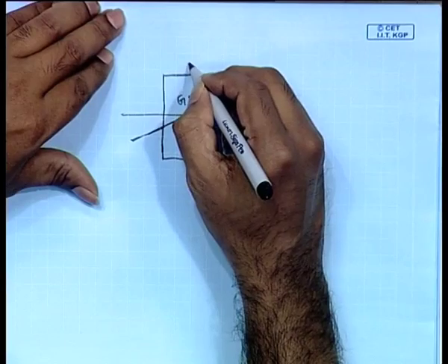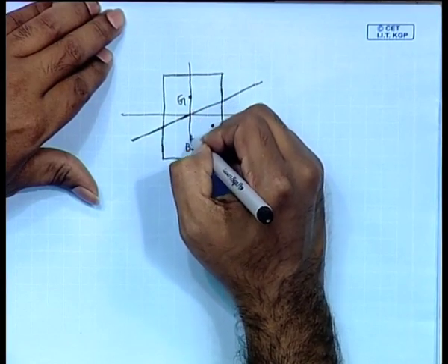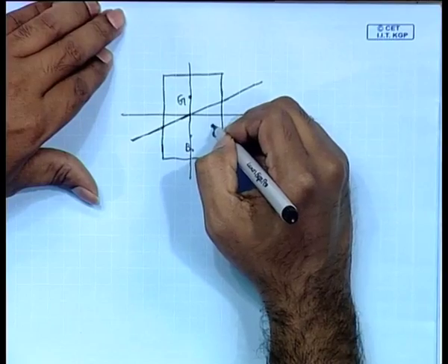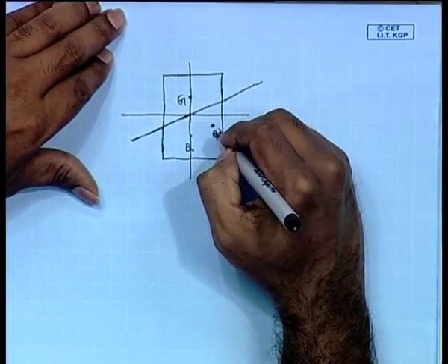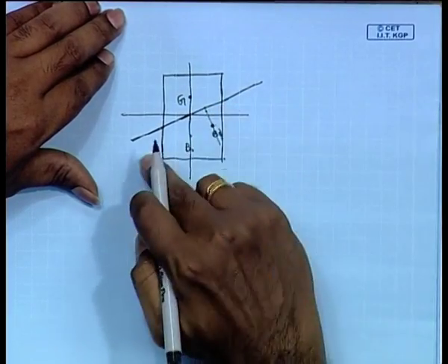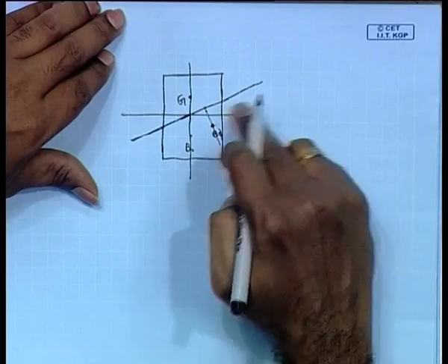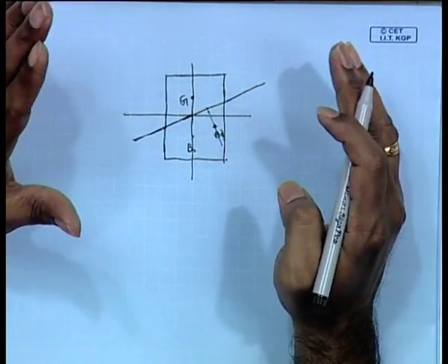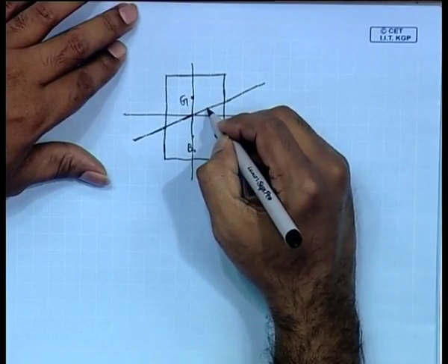So, this is the initial vertical, and if I draw a vertical from here, you have to remember this is the water line, this is horizontal. Even though it looks inclined in this figure, the line is actually horizontal. It is the horizontal water line that is drawn here, and a perpendicular to it is always the vertical line.